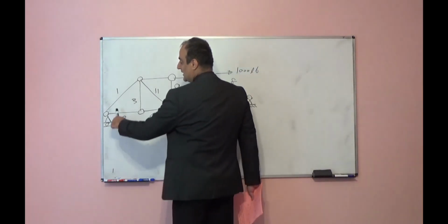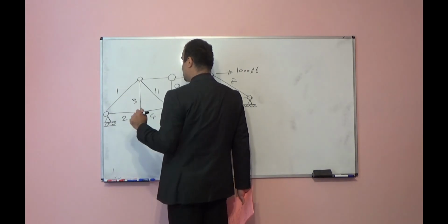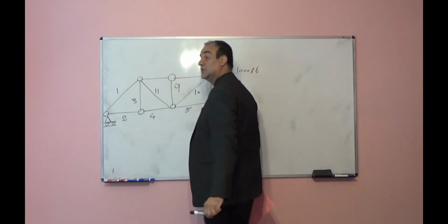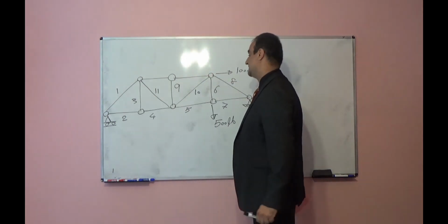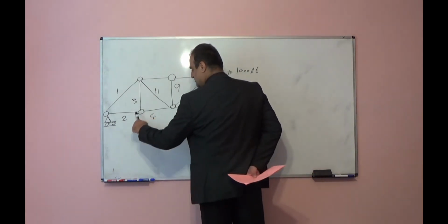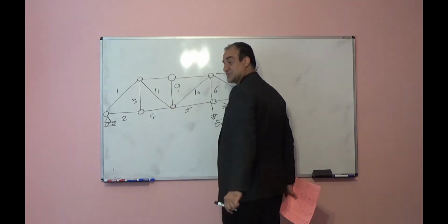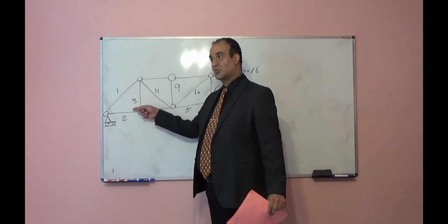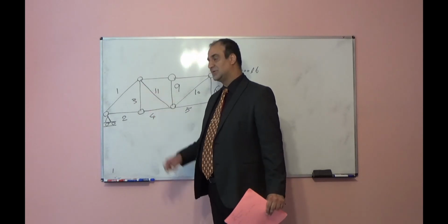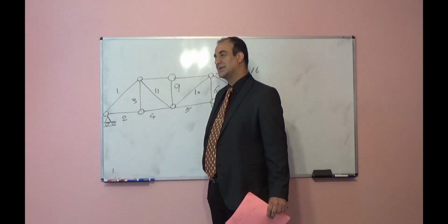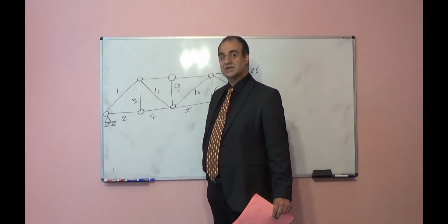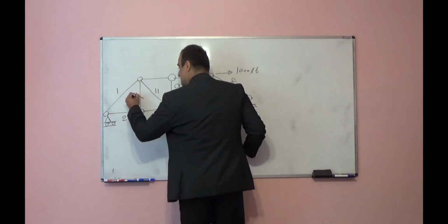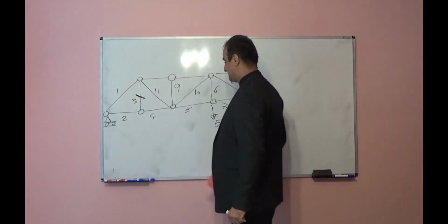This joint, two members, but we have a support, so we cannot tell. This joint, 1, 2, 3, 4 members, we cannot tell. This joint, 1, 2, 3 members. Two members are in one straight line, they are collinear. A third member is perpendicular to that, and there is no external load at this joint, so this one is a 0 force member.